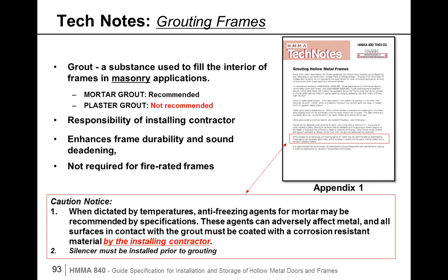In HMMA 840, the technical tip for grouting of frames is critical. The key thing in this publication is that mortar grout is the grout that is recommended. Any type of black plaster grout is not recommended due to corrosion. It's the responsibility of the contractor to not only protect the frame for grouting, but also to do the grouting.